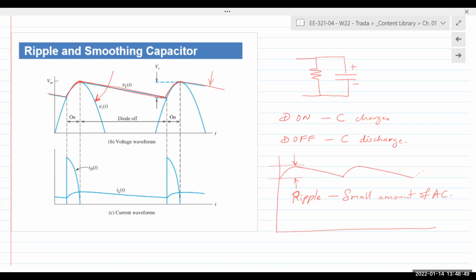So all put together, the kit I passed out is probably like 10 bucks or so. So it's not that expensive. Anyway, the point I was making was the larger the capacitor, the longer the time constant, and the longer the discharge time, and the flatter your output waveform, and the smaller the ripple.